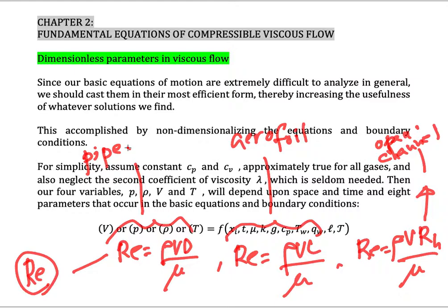So I hope when you do your research, please choose carefully what parameter you want to substitute in your dimensionless number. And every dimensionless number has its own physical meaning. For example, the Reynolds number, the most famous dimensionless parameter, shows us whether the flow is laminar or turbulent. After a certain value of that dimensionless number, the flow is turbulent. But you must make sure that you know the transition, the boundary, the borderline.